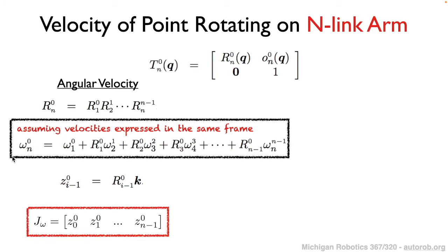As a result, if we take the partial derivative of the angular velocity with respect to one particular degree of freedom, one of the joint angles, what you'll find is that it ends up being that particular axis of rotation rotated about the corresponding rotation transformation of that specific joint. And so this is how we derived the values that were used within our particular column vector, making up the angular portion of the Jacobian.